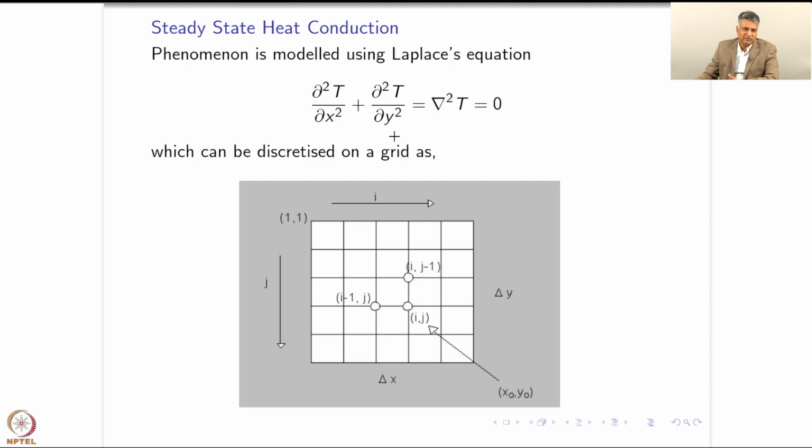Now, the next thing that we need to do is to discretize this plate, in the sense that I will now take information at a finite number of points within the plate. Again, what spacing of points I should use depends on how accurate I want the answer to be and how useful that data is going to be. As I said, let's say that this plate represents the grid of a city, and these are different locations in a city. Let's say that we took a very flat city in the country and modeled it as a plate, and we're just looking at heating from some fire which is coming at the edge of the city.